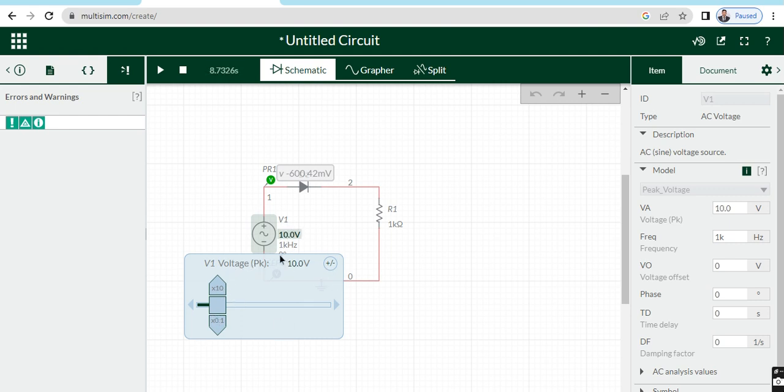If you again click on 1 volt, here at the bottom you can see 0.1 multiply, so click here, so it's again 1 volt, and you can simply slide it and increase or decrease the voltage. So if we need to set it to 5 volt, okay, slide it, okay, it's 5 volt, right?